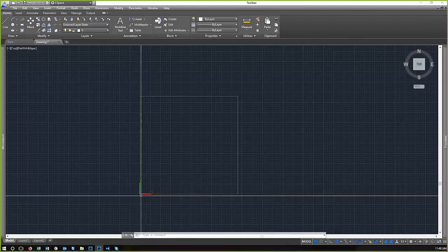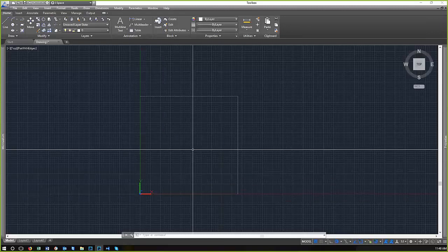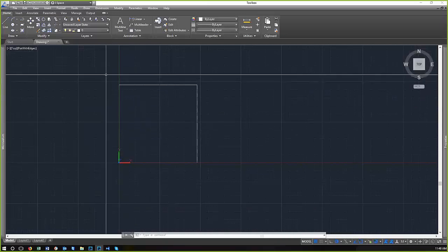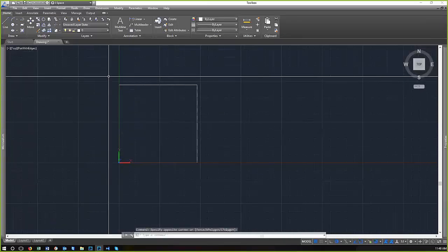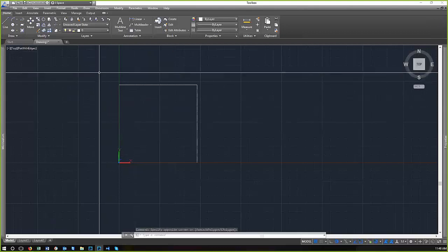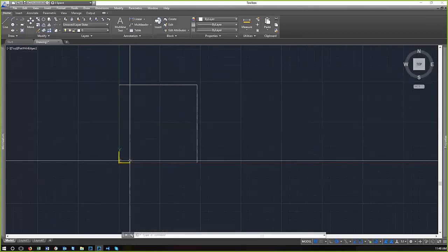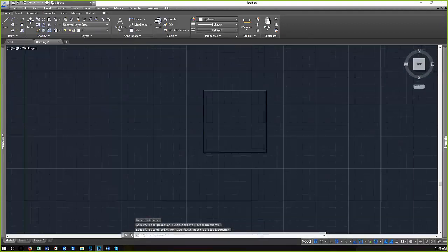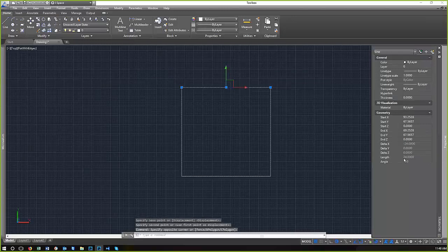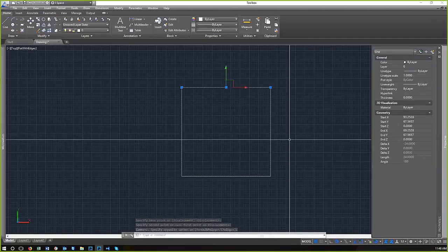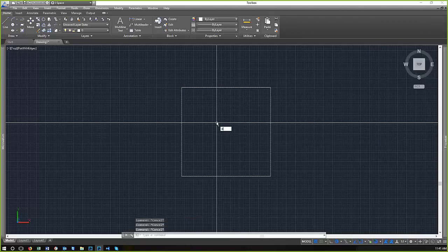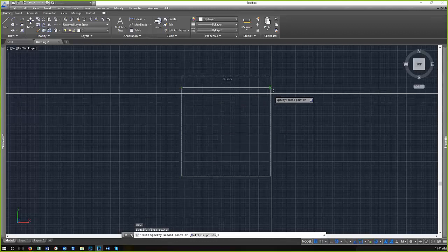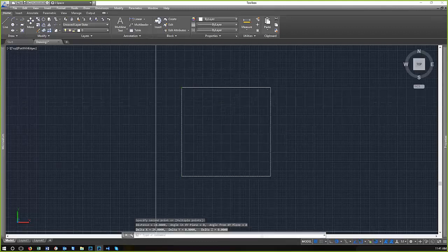So starting a drawing at 0, 0 can be helpful, but also keep in mind that all of your drawings, regardless of where they are, can stay relative to each other. So you can measure objects such as this box. If I didn't draw this at the 0, 0 coordinate, I draw it somewhere way over here, I can still get the length off of that and see that it's 24 inches long. Or you can use a DI command and select, and that gives you the distance.